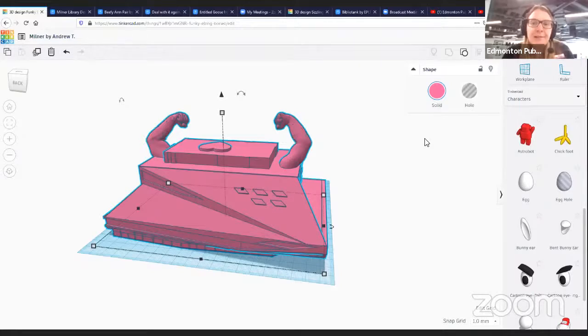And if we had two separate volumes that were intersecting and they were considered solid objects, if we didn't group, then we would have instructions that would cause problems for a 3D printer if we actually tried to run them. We'd probably get some software warnings, but it's a good thing for us to be aware of and to potentially avoid. So in terms of that group command, what we're trying to do is get the model into one single manifold volume so that we don't have anything that's intersecting where it shouldn't be. We don't have anything that's going to cause problems as the 3D printer tries to carry out the manual commands.